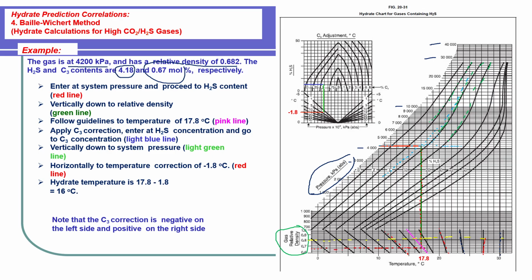Okay, now I'm going to draw a line that represents my temperature, but the line has to be inclined in the same way that the lines before and after are inclined. So I'm going to draw a line here at the intersection between my pressure value, the H2S content value, all the way down vertically to the specific gravity value, and this line represents the hydrate formation temperature, which is going to be around